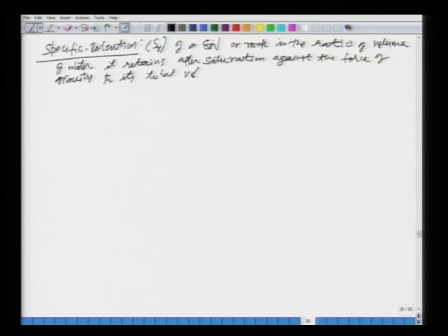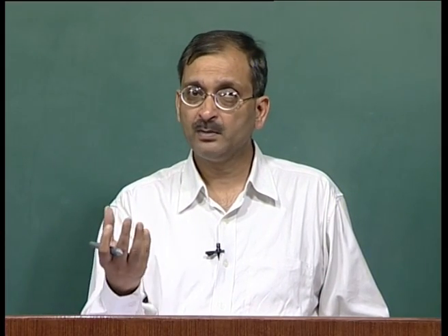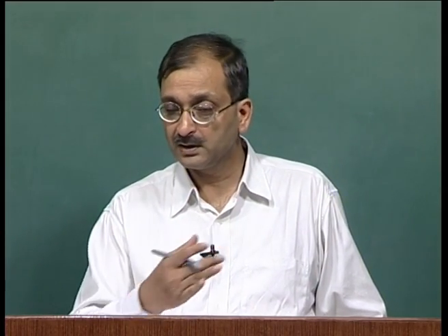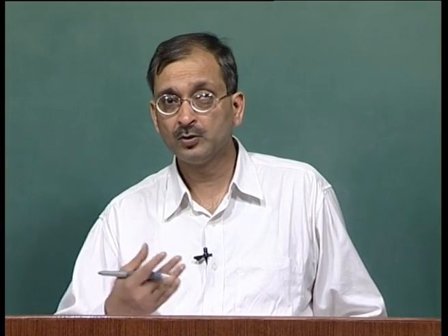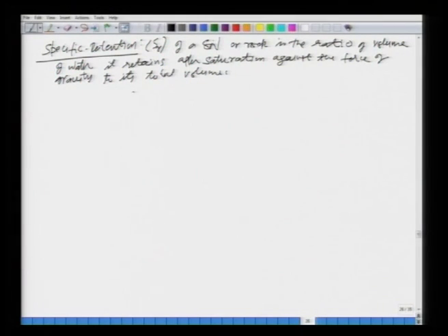What we are saying is that it is the ratio of the water retained by the soil against the force of gravity, meaning water being retained by suction or some other forces, after the sample has been thoroughly drained due to the gravity forces, to its total volume. So if we define it, S subscript R will be V R over V T, and using the equation numbers we have been following, let me number this as 15,